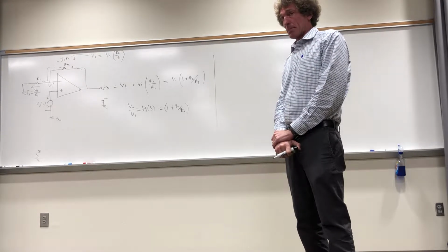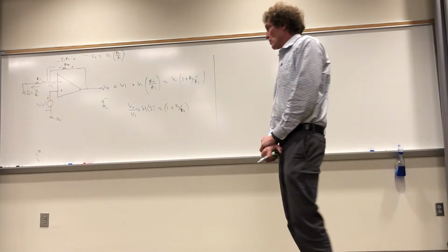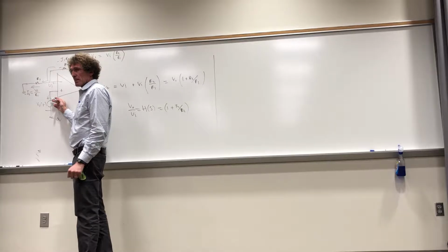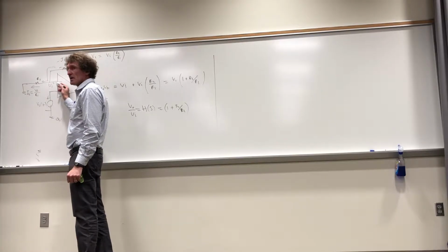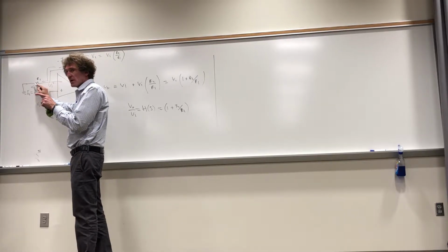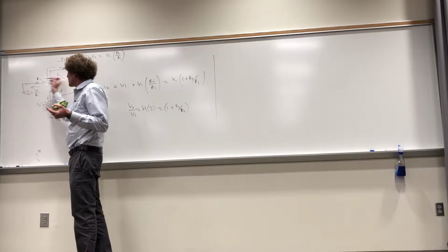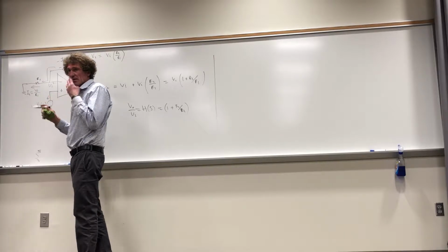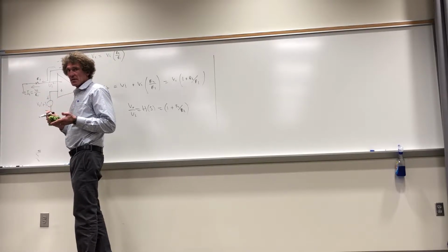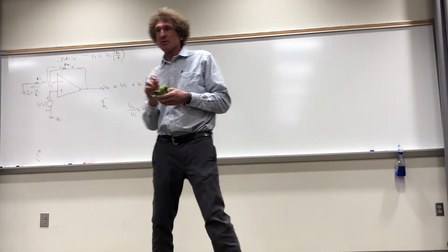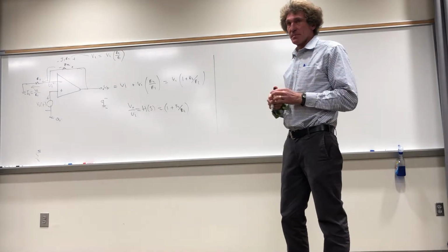So how did you choose the direction of the current, or is it set because of that voltage? Well, I chose this as a positive polarity, right? If this is Vn here, that's positive Vn here, right? The current is always the voltage on the one side minus the voltage on the other, divided by R1. If Vn is positive, the current goes that way. If Vn is negative, the current goes the other way. But you don't care, you define it in terms of Vn. Understand, class? Vn determines that. I chose the direction going that way because I'm assuming Vn's positive, just for simplicity.